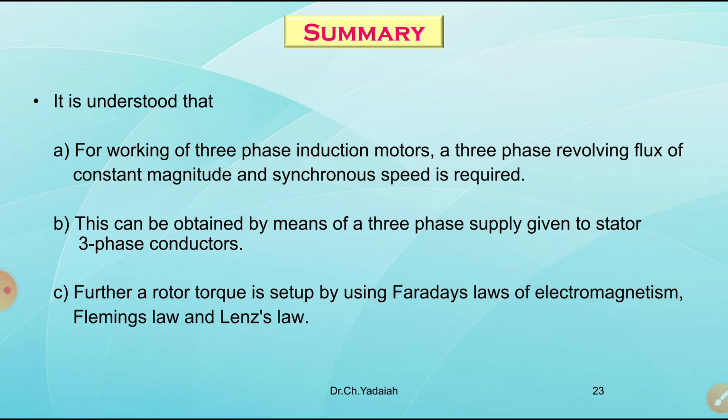We concluded that the rotor magnetic field and stator magnetic field both run at synchronous speed. The relative speed between these two is 0, but the rotor is running at normal speed. The frequency induced in the rotor depends upon the slip speed. Supply frequency into S gives us the rotor frequency.